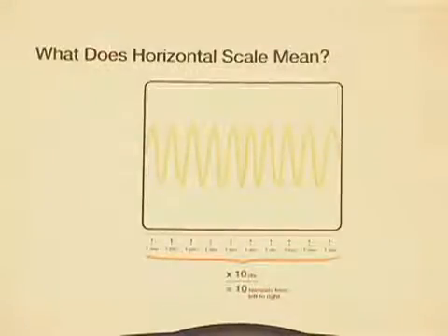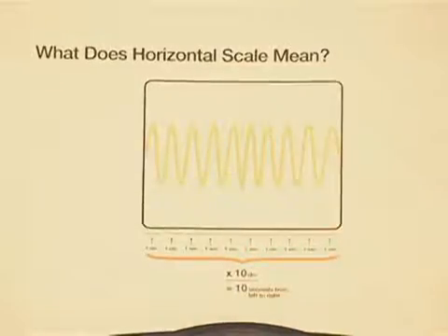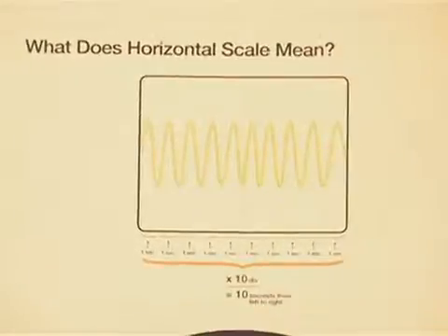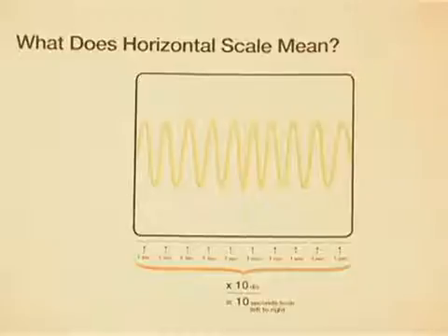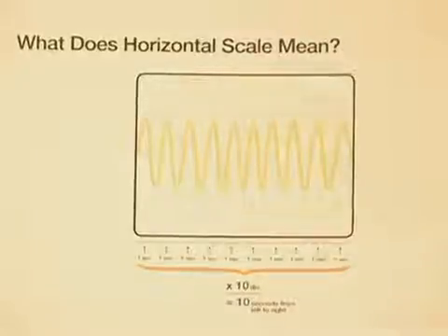And horizontal scale is expressed in seconds per division. So if you have 10 horizontal divisions available on your screen and you have your scope set to 1 second per division, that means you can fit 10 seconds worth of data on the screen. Oh, that's great. That's really similar to the vertical. Exactly. Just a different... Can we see down on the screen also? Yes.